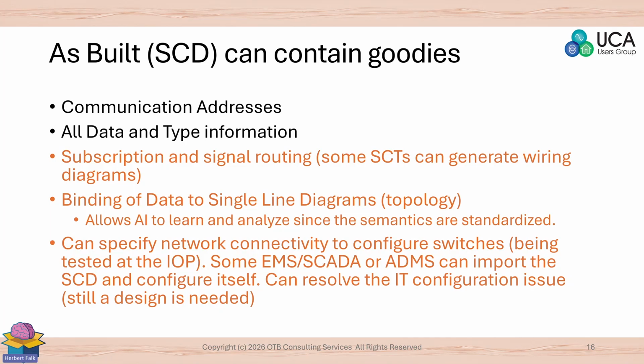You can specify network connectivity for configuring switches. And at the interops, we are actually testing, can we configure our network of switches based off of an SCD? Some EMS SCADA systems or ADMS systems can actually import the SCD and configure itself and potentially even generate the single line diagrams off of it. So there are lots of benefits to using SCL today and in the future.